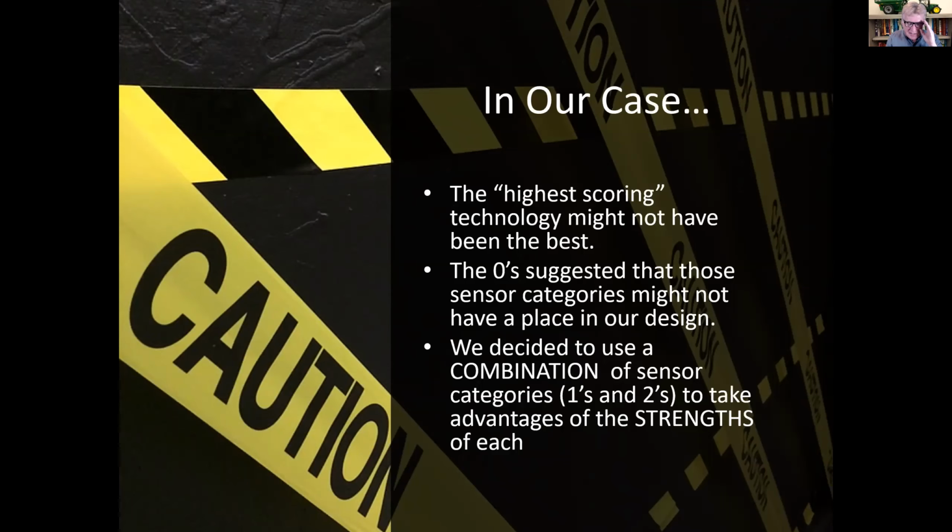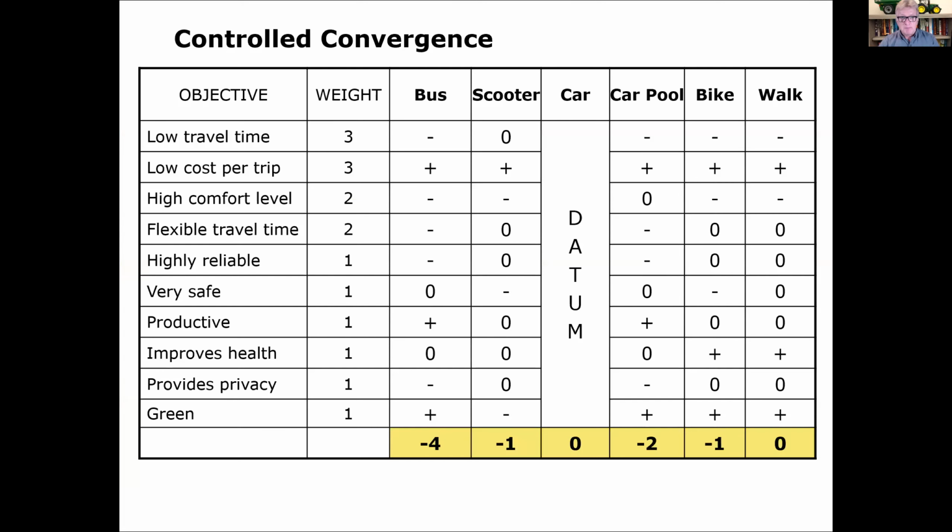I think in the end, we ended up using a combination of radar. So we have the Doppler effect of a sensor seeing an approaching person and their velocity based on the Doppler shift, but then we also used infrared, so that we could detect the person's heat signature, their infrared body temperature. That would also help us distinguish between a tree blowing in the wind and a person who actually emits infrared heat energy. And so this design matrix was just so valuable to help us make a smart decision.